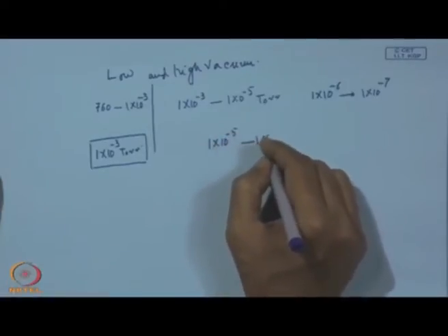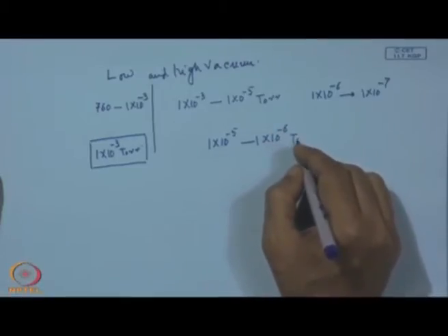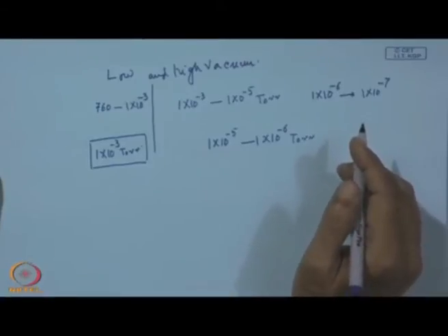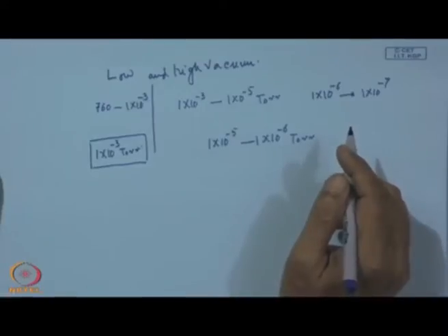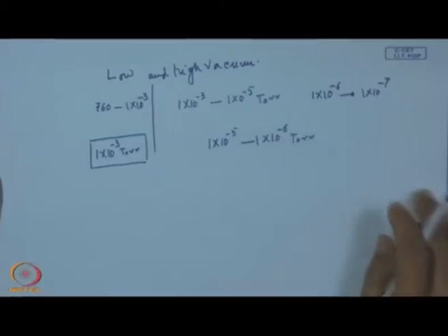Now, when it comes to a PVD process, cleanliness is of extreme importance, and in that case a pressure between 10 to the power minus 5 to 10 to the power minus 6 as a pre-evacuation is most demanding, and we cannot compromise with this base pressure, because the residual oxygen present in air can also cause contamination of the target, particularly those transition element targets which are very reactive with atmospheric oxygen, polluting the entire chamber, which may ultimately lead to poor quality of the coating.